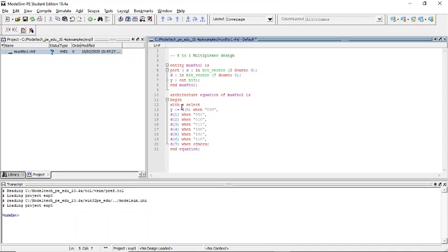With is a keyword. With S is the selector input. Based on the selector input value, you are going to select one of the data inputs as the output. Select is the keyword. Now Y is the output. So Y is less than or equal to, it is an assignment operator in VHDL, D0. So when selector input is 000, then D0 will be selected.